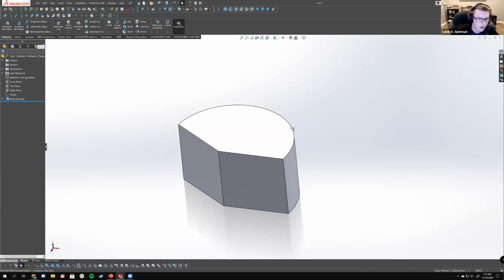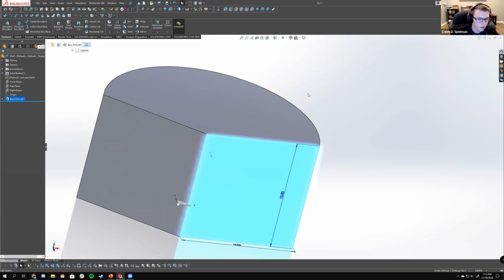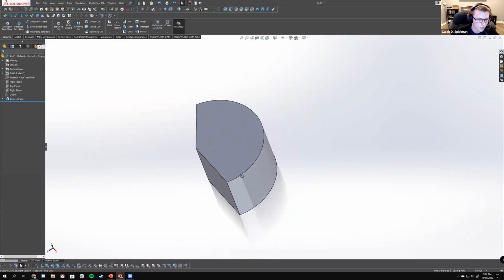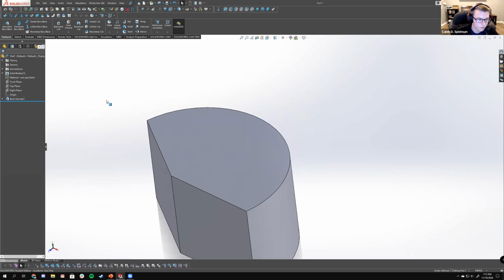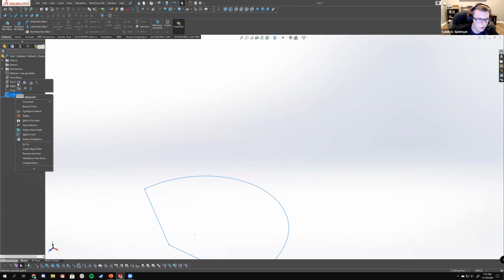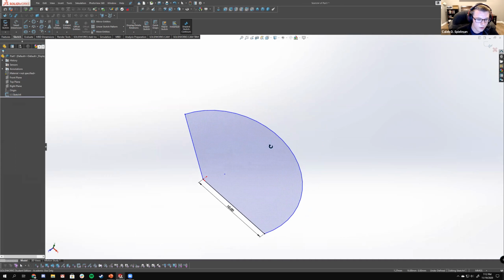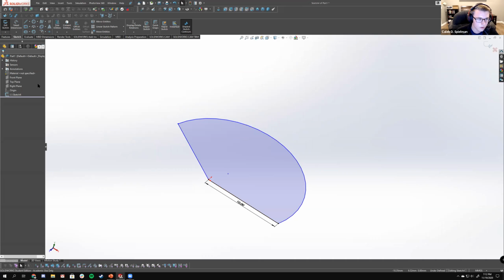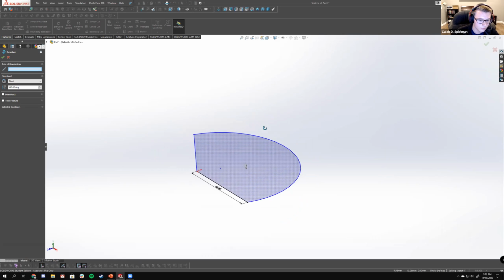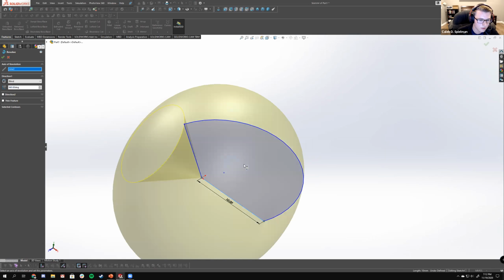We can check that. And now we have a solid body. Defined from that 2D sketch, we have just made a volume. Very cool. Now I will show you another solid feature. So here in this same sketch, we can use another boss/base tool, which is the Revolve. We can use this contour and essentially rotate it 60 degrees around an axis. So I'm going to choose an axis.